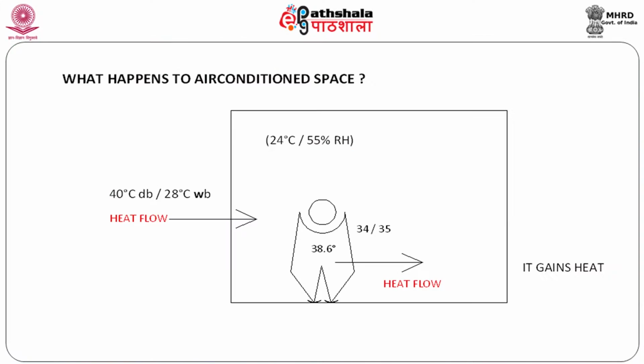Now, at this parameter, research has established that a person is most comfortable if his environment is at 24 degrees, which means air conditioning temperatures have got to be 24. Now, 24 is also related to a couple of other parameters which are very strong on the air conditioning man's board. These are relative humidity and air movement. At 24 degrees, one wants 55% RH. At these conditions, what you do not see in the slide, you require a small air movement across your body, something like 25 feet per minute.